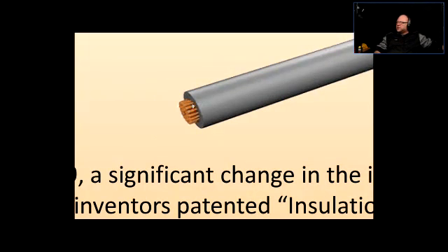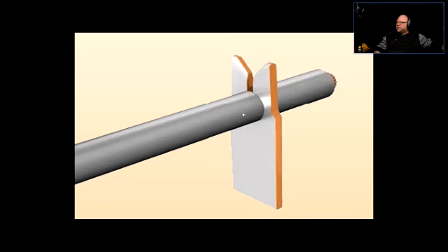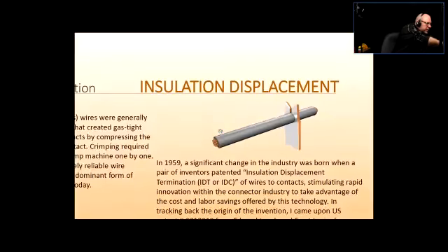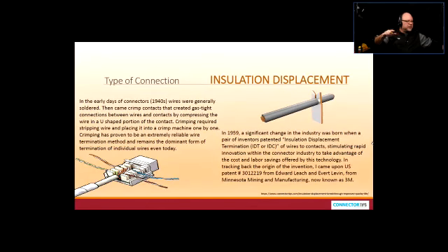For this reason, the IDC, insulation displacement connection, should be done with solid conductors only. It's designed for that kind of conductor. No stranded wires, solid wires, solid core. All right. And here's the reference to the picture here, and you have this already in the posted notes.